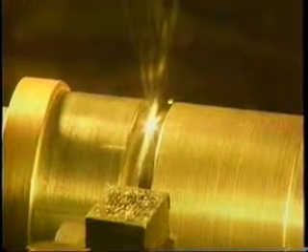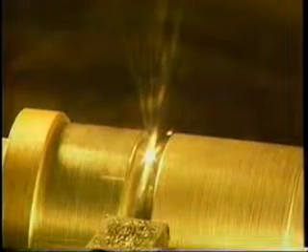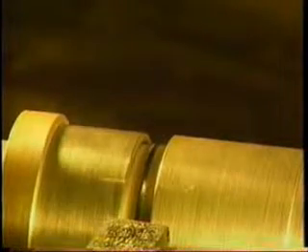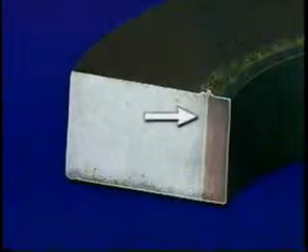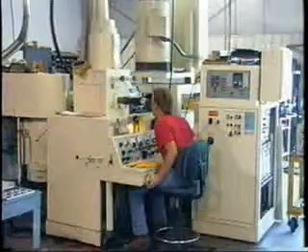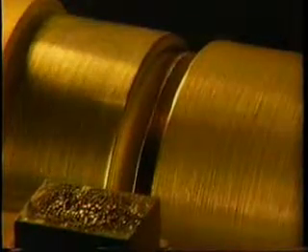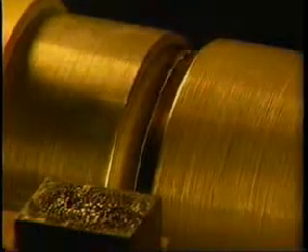or standard atmospheric pressure. Because of the intense and concentrated heat generated, total heat input is low, minimizing heat-affected zone size and part distortion. This also allows for the creation of extremely deep and narrow welds. Additionally, joints inaccessible by other welding processes can be welded. Virtually all ferrous and non-ferrous metals, thin or thick, can be joined. Welding speeds are fast, and filler metal is not generally required. Equipment cost for electron beam welding is typically high, and welding is generally limited to machined parts assembled in primarily butt, corner, and lap joints.